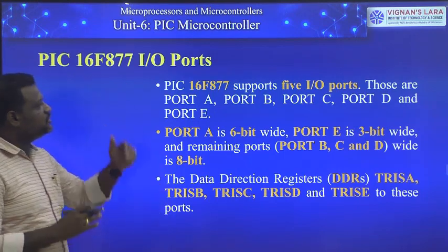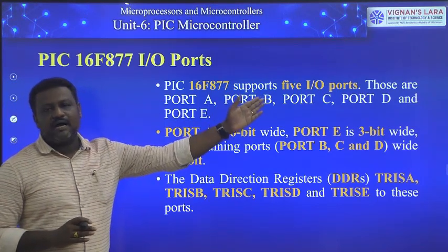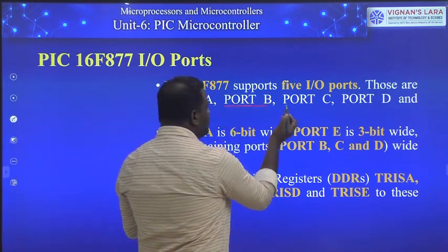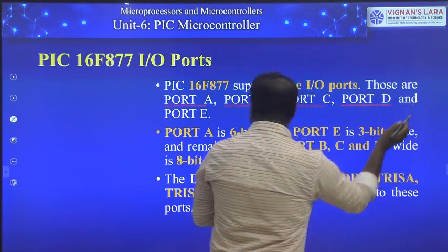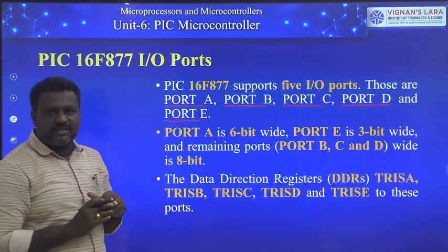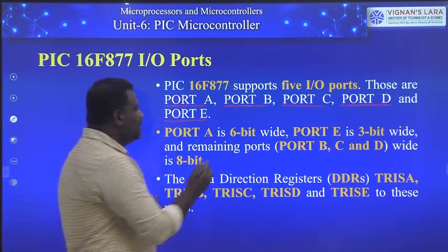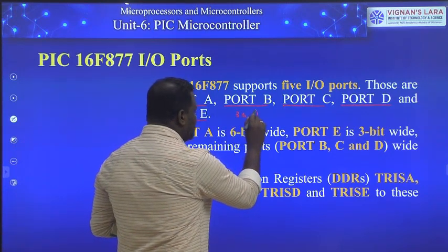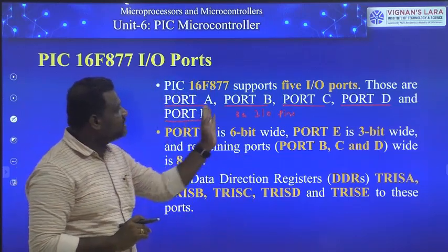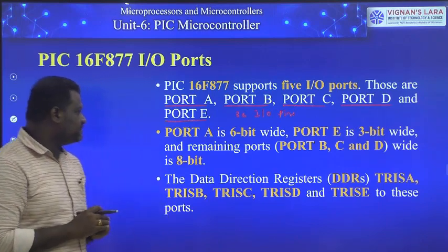My first point is that PIC 16F877 supports 5 I/O ports: port A, port B, port C, port D, and port E. And this particular PIC 16F877 has a total of 33 I/O pins, organized into these 5 I/O ports. That you have to remember, friends.